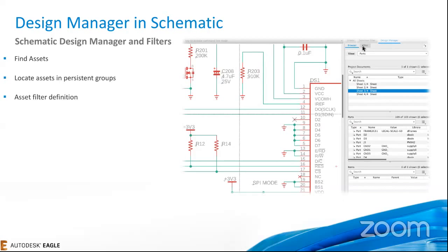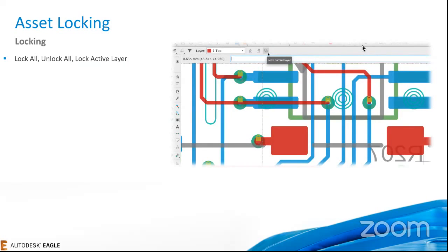Let's say you're looking for all the components, and Jorge made this comment the other day, all the components that do not have 3D models assigned to them, or components that do not have SPICE models assigned to them. So you could create a filter for those, and you could actually save those filters. That way they're persistent on the current design or in other designs. They could be permanent, so they could recur in every design that you have, and then you could just select those filters. So let's say you want to look for all your resistors of a range of values, you could do that as well. Jorge will be demonstrating this in a minute as well. And we'll be taking care of Q&A towards the end, so don't worry about it. I will be tending to that in a few minutes, okay?